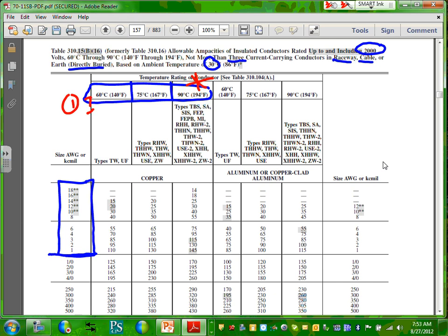I is for amps. If your I is 100 amp or less, if you have a piece of equipment that's 100 amp or less, and you have no idea, Jeff, about the lugs on both sides, no idea, they don't tell you what the lugs are, what's your default? 60. From the get-go. Can I have a thumbs up? We got that one? Cool.